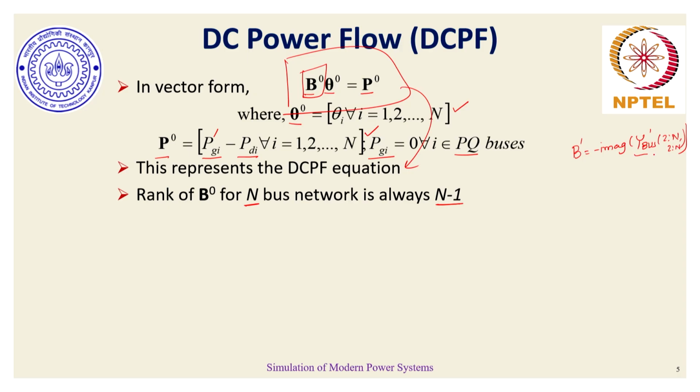Y bus dash, if we evaluate it, considers only phase shifters and line reactances, so the imaginary component also has no actual information with respect to connection to ground. Essentially the connection to ground is lost and unique bus voltages should not be obtained, although there are ways we can obtain them.